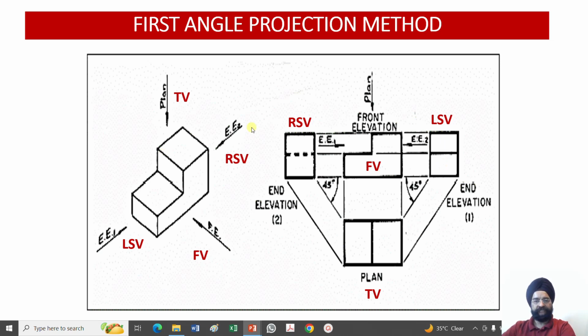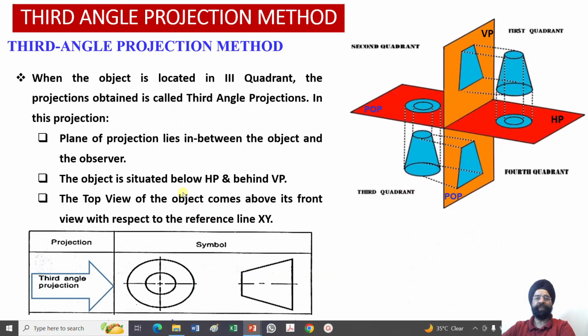But if you look at this object from the right, you can see this complete surface over here, but this notch or this cut you cannot see. Since you cannot see this cut from the right hand side, this line has been drawn dotted. So the right hand view has been drawn on the left hand side with this cross section shown dotted over here. If you look from the left, this will be visible. You look at this object from the right, this edge will not be visible.